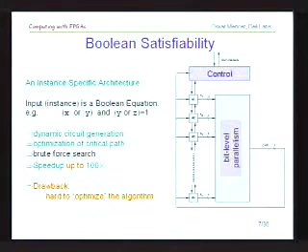So what you can do is a brute force search, where all you need to do is evaluate the actual equation that you have many times over until you find a possible solution. And using an FPGA, you can take the equation that you want to satisfy, put it down into the FPGA, and simply evaluate it very quickly, because now it's just a circuit in your FPGA. So you have an instance-specific way to configure these FPGAs at runtime. Whenever you get the data from the user, you simply create the circuit, put it in the FPGA, and evaluate it as part of your execution.